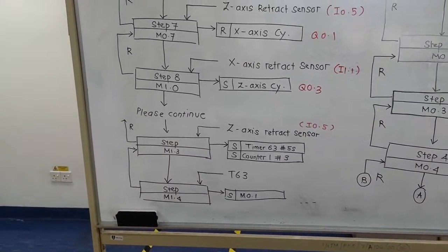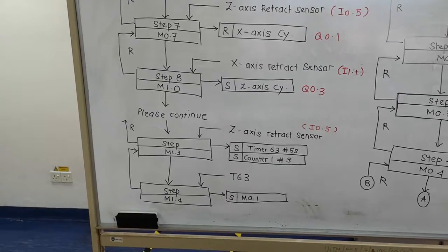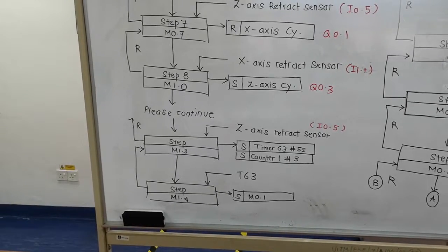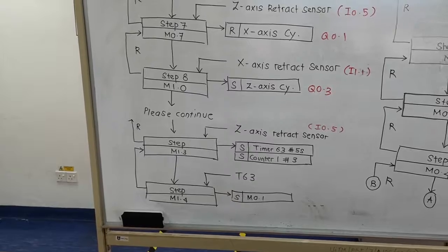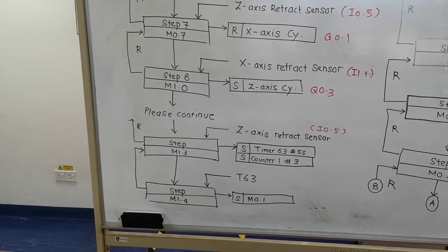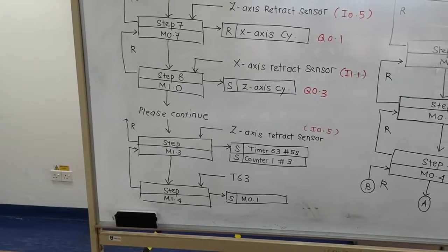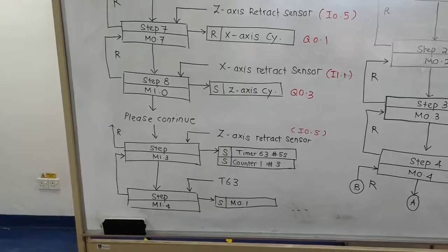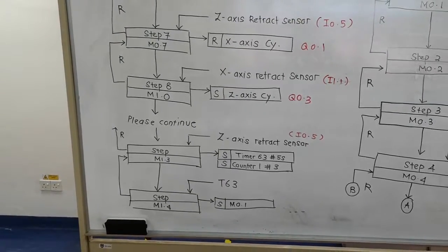Alright, what I have to do at that moment is trigger a timer. So at that moment the timer is triggered to delay the process, and then that timer will be used to trigger the last step. And then the last step will be used to trigger the first step again. I don't put the number of steps because this depends on your programming. If you notice, there is a counter there, but later on I will explain. So now we move on to how to make the looping process and also include a timer.